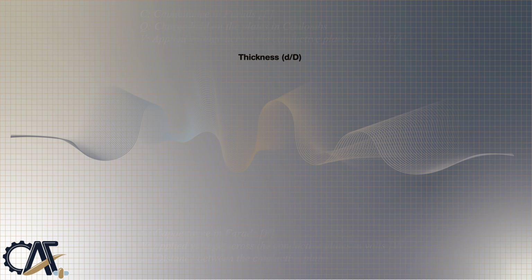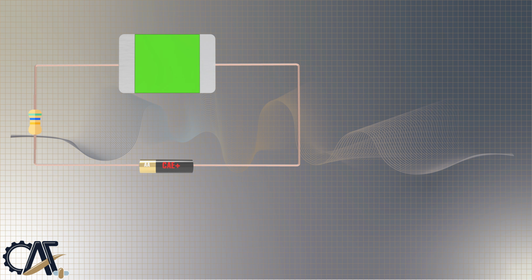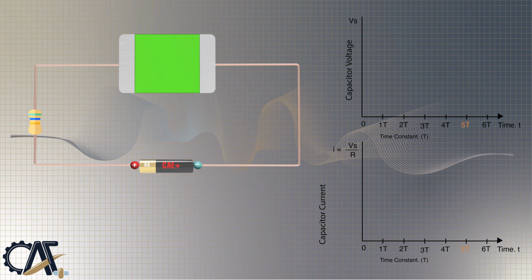To understand how electric energy is accumulated and depleted in a capacitor, we need to add a resistor to the previous circuit to make an RC circuit. By applying a voltage to this circuit, an electric field is formed between the plates, which makes the capacitor a way to accumulate electric energy. As shown in the capacitor charging graph on the right side, the capacitor voltage increases until it reaches the voltage level of the source. By then, current cannot flow any longer.